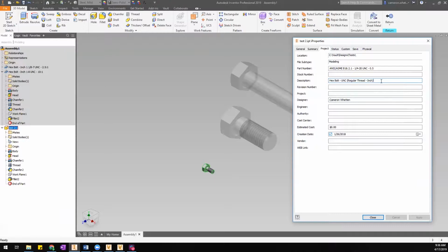And so if I place it as custom, I can go in here and type in a better description. And that's a good change, right? That's something that would actually be useful to have. But if I'm just going in here and placing every part from the content center as custom and then manually changing the description, sure, that's fine for me for this project.